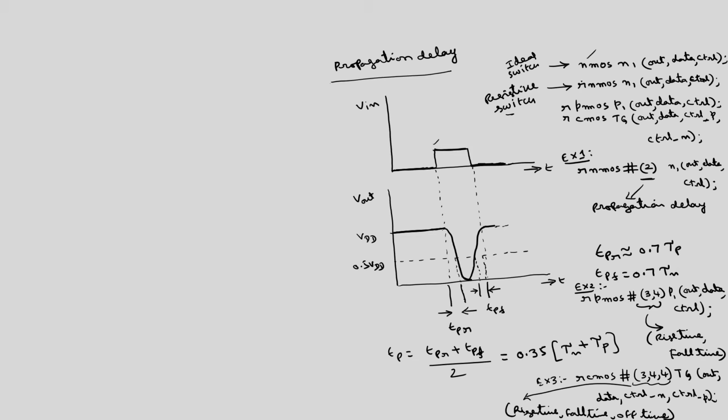So, till now we have discussed the various primitives of switch level modeling. These are nmos, rnmos, pmos, rpmos, cmos, rcmos, and then supply0 and supply1. These are the various primitives that we have discussed till now. There are some more primitives such as pullup and pulldown.